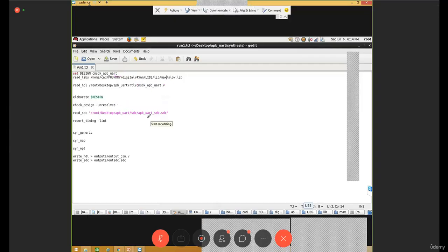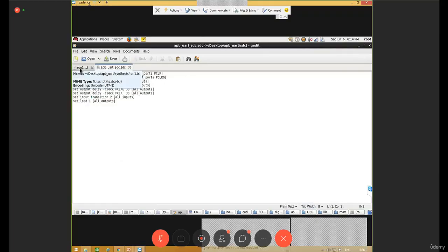As of now in my design I have two clocks. So I need to give the clock frequency for those clocks to propagate into the sequential cells. The command to give the clock is create_clock. How you will get to know the command, I will show when I execute things. So create_clock is a command to give the frequency.